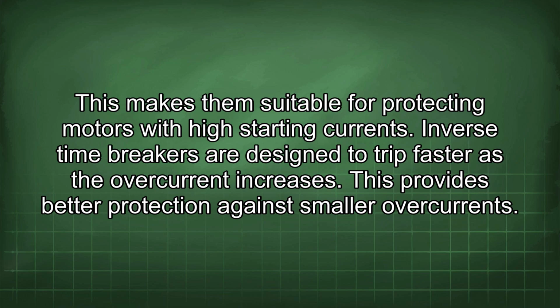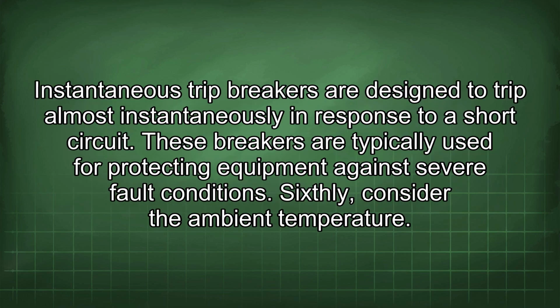Inverse time breakers are designed to trip faster as the overcurrent increases. This provides better protection against smaller overcurrents. Instantaneous trip breakers are designed to trip almost instantaneously in response to a short circuit. These breakers are typically used for protecting equipment against severe fault conditions.